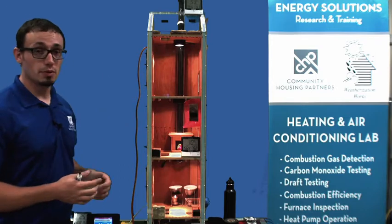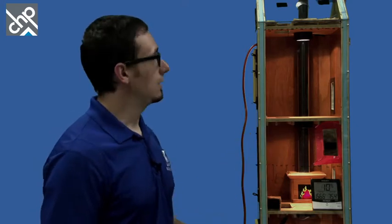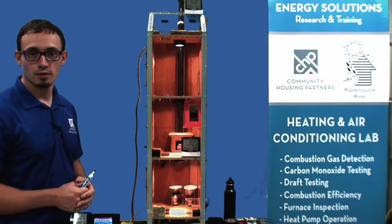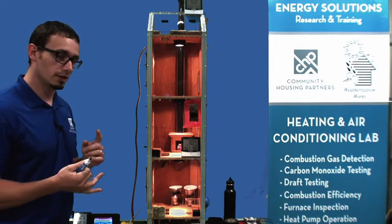I want to start at the top of the building because that's going to have a great effect on that neutral pressure plane. And second, stack effect is typically greater in the wintertime. You have a greater delta T in the wintertime. So if I want to cease this heat flow, I want to seal this location first, because if I stop the air from going out in the first place, I'm certainly going to stop the air from coming back in. Okay, so we've discussed our heat flow mechanics of conduction and convection.